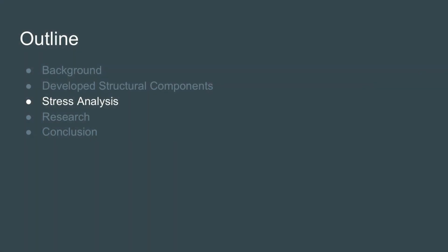So now we'll discuss the stress analysis. After the completion of the assembly of the spacecraft, each component was analyzed using SolidWorks simulation software to ensure that they would hold up to the pressures that would be faced in space. In order to do this, we ran a static pressure test at 1 atmosphere to simulate what the modules would be facing in orbit. And each module was simplified down to a single layer for testing.